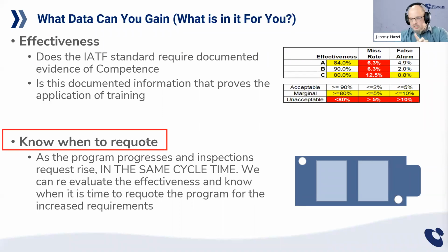Now, I want to give you a real life example on this. I used to do injection molding, and we had a part that came through, and they wanted us to visually inspect for flash around the parting line. Flash around the parting line, for those of you that may not know, is plastic that we then have to trim off, cut off, whatever it is. It's right here. And so we wanted no flash along the parting line. And we gave the inspector 15 seconds to do this inspection.